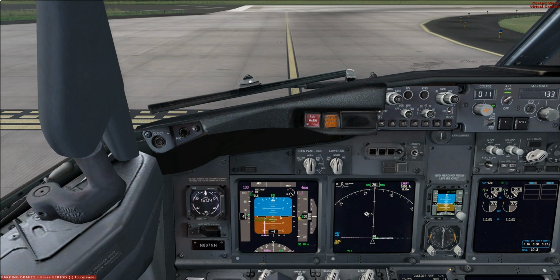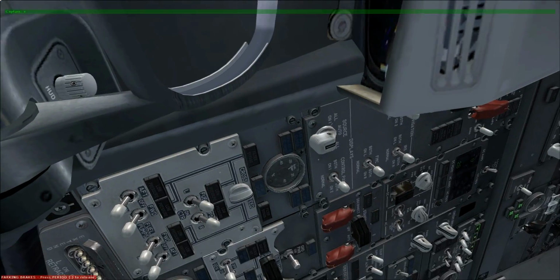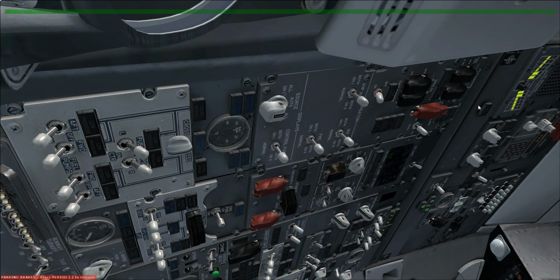The second type of alert is called a reactive wind shear alert, and this type of alert comes from the aircraft GPWS and is triggered when certain parameters are met or exceeded, including the indicated airspeed, I think the vertical speed, and I think if there's a certain amount of change in the wind speed and direction as detected by the inertial system here.